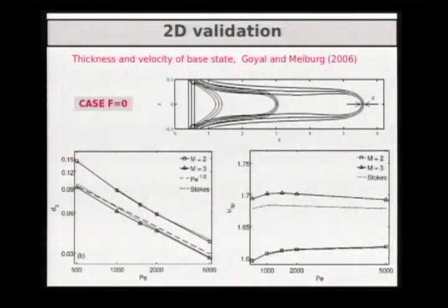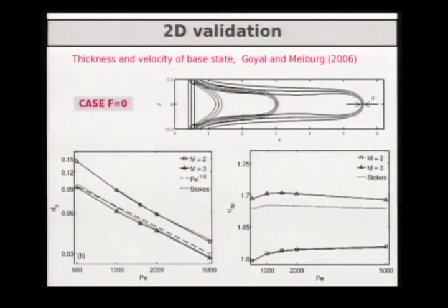Our results are in the continuous line, and the dashed lines are the 3-dimensional Stokes calculations, and they agree within error below 2%. Our Reynolds number is kept small at 1, so the 2 theories should agree pretty well. We also measure the front velocity that is plotted here, and the comparison to the Stokes results is also very good.